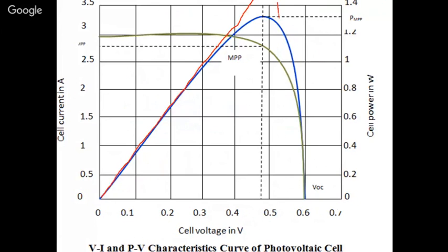Let me again draw the slope here. So this slope is a negative slope, so I've crossed my MPPT point. And when my slope is 0, I have reached my MPPT. So that is nothing but your incremental conductance method. They just find the conductance, current by voltage, you just have to do dI by dV. That method, if you see, is just like P and O only. That is also a calculus method only. You are just trying to find the peak in different methods. So this is the general conventional method of finding the MPPT point.